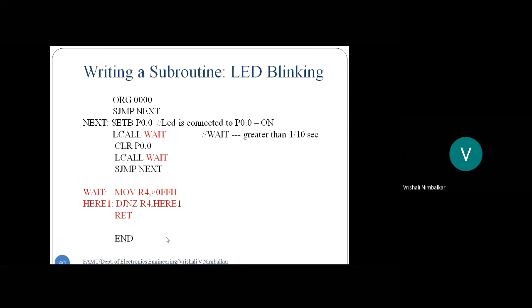Right? Are you getting me? See here, students, in my program, SP is nowhere mentioned. It means SP will begin from 7 hex. And if I allow this to happen, the bank memory and the stack memory get overlapped. Okay. So to avoid this problem, the stack memory is allotted at the last locations of internal RAM.